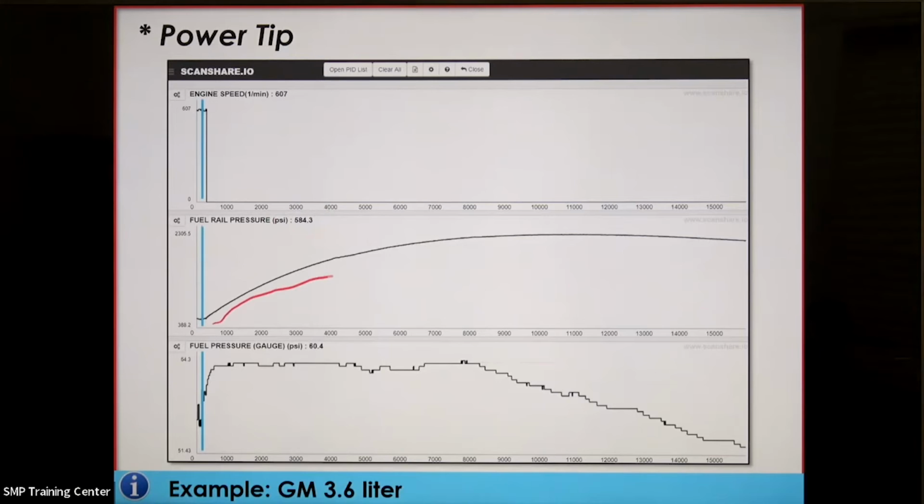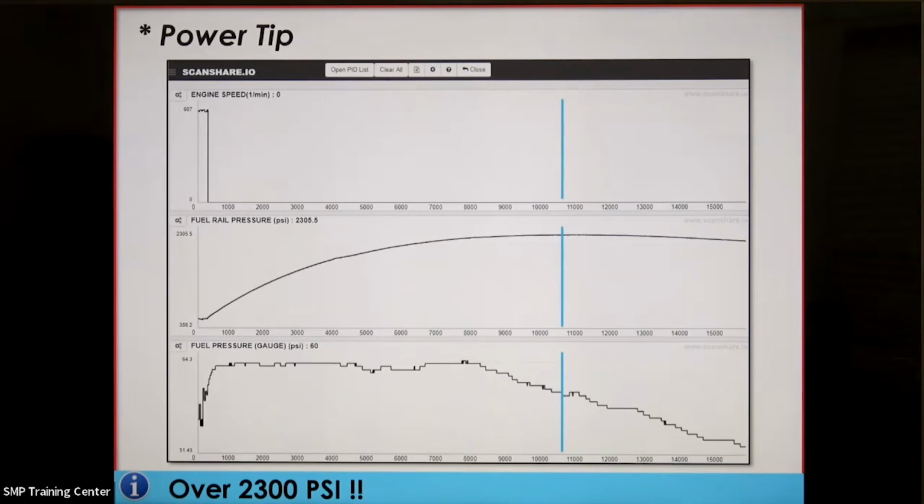Well, it started increasing, climbing, going up, up, up. In fact, after about 20 minutes, which you could liken maybe to the time that it took you to pop the hood, raise the hood, and start gathering up your tools, you are ready. 20 minutes later, you've got your wrenches in hand and you're ready to break tension on that high pressure fuel line that you're about to take loose. But guess what's on the other side of that connection? Waiting for you inside of that line is over 2,300 pounds of fuel pressure. Let me tell you, folks, that fuel is not going to come out of there like a razor blade. No, no, no. It's going to come out of there like a sword.